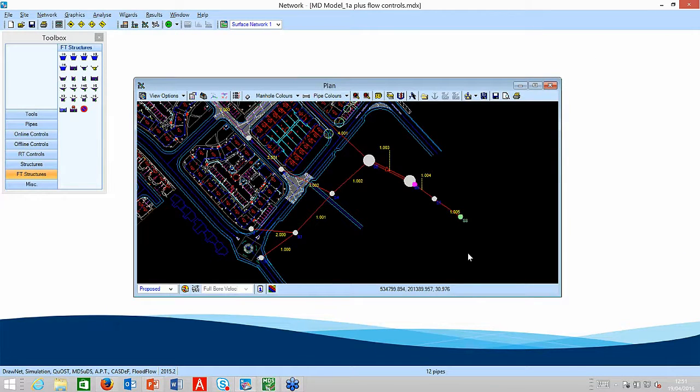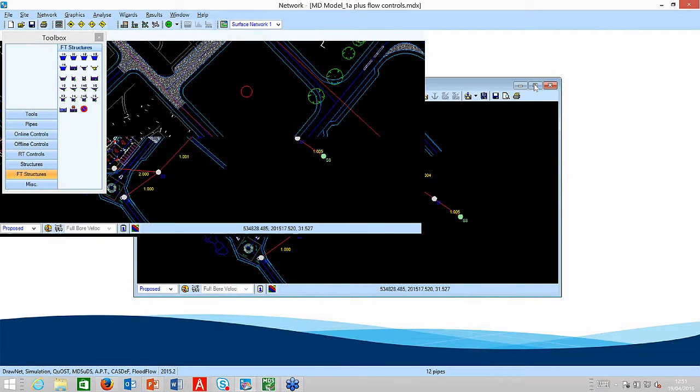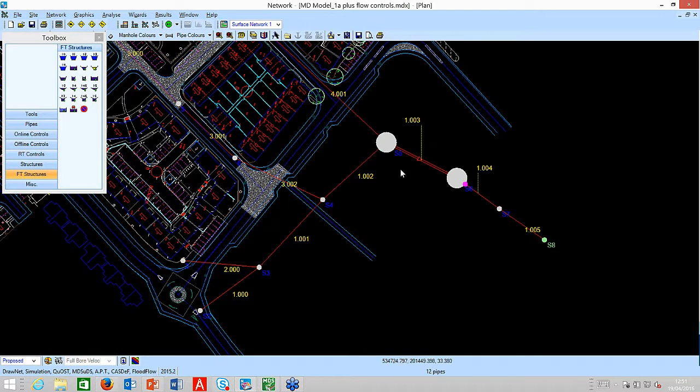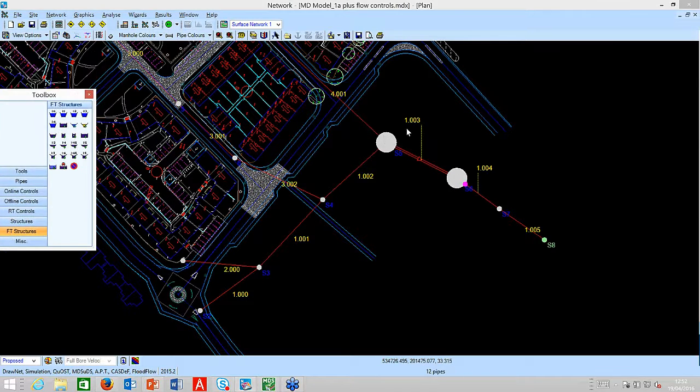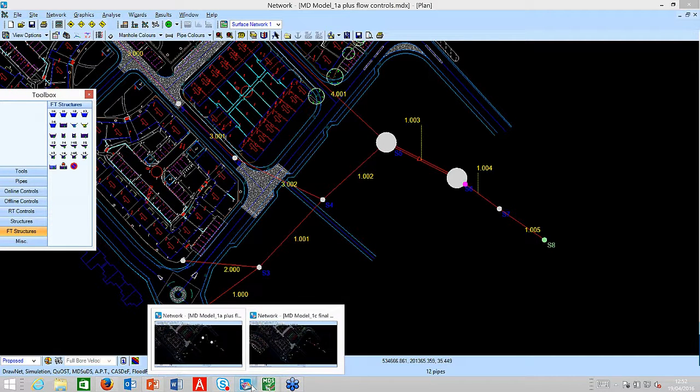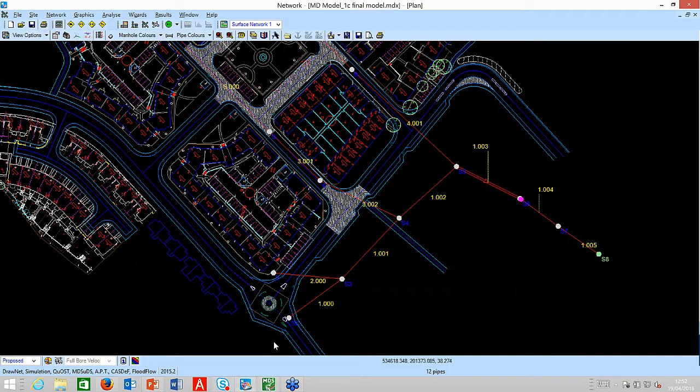because we're replacing a pipe, you can now see it's a double line with an arrow on there. A couple of things have happened. It's made the manholes look ridiculously big just to capture my eye, to say, look, you've dragged and dropped a structure to replace a pipe. So you now need to consider your model. So I might just go in and correct the manhole sizes. But if I go to my Blue Peter, because I'm looking at the time and it's running out fairly rapidly, what I've done is I've downsized my manhole sizes.